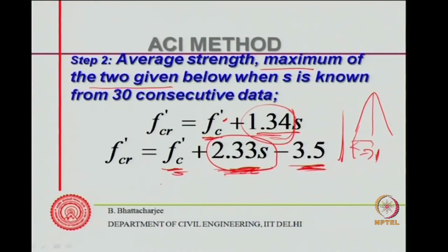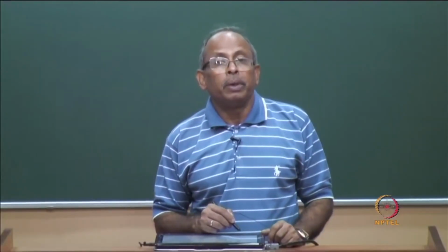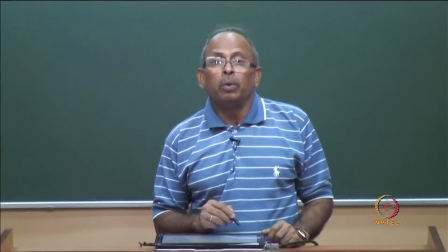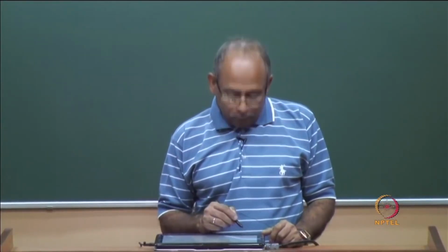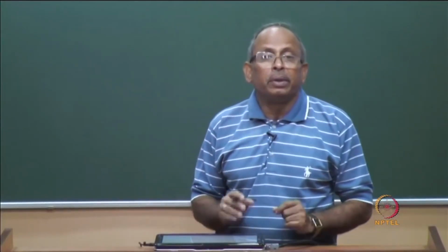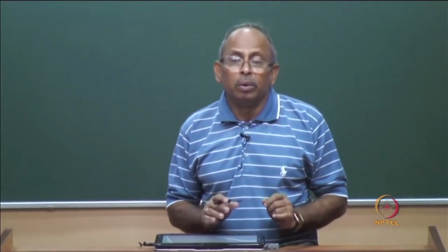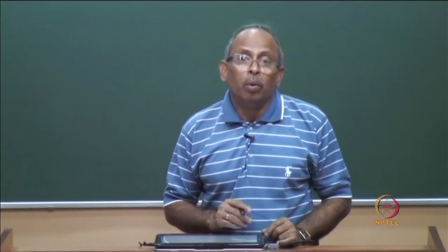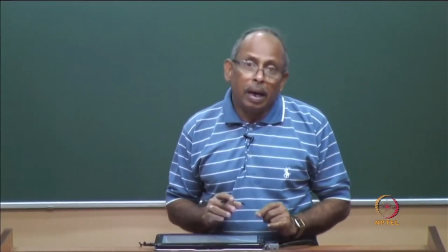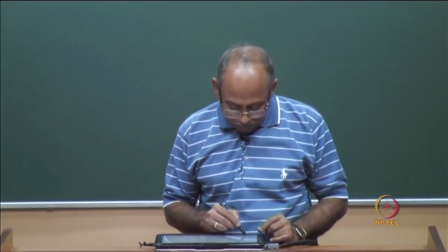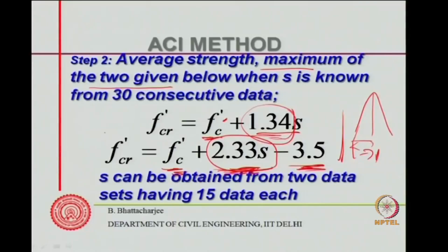the water cement ratio. So, you have found out the water cement ratio, and we have also found out the water content. For this, again I repeat, it is all for the cylinder strength. So, average cylinder strength is known, and therefore, correspondingly I found out the water cement ratio. And when I found out the water cement ratio, also the water content, I should be able to find out the cement content.